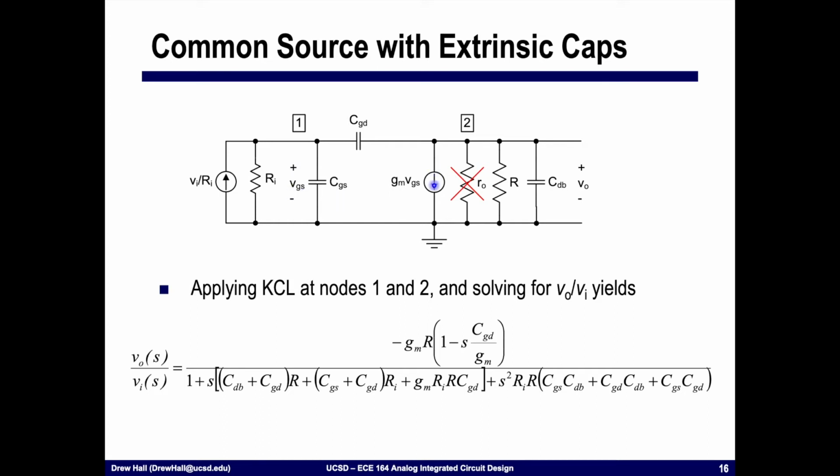This would then go through this transconductor to turn into a current, and it would get reflected back into a voltage at the output by the output impedance. Okay? What happens with CGD is it lets the signal race forward to the output through this capacitor. And so it provides an alternative path to the output.